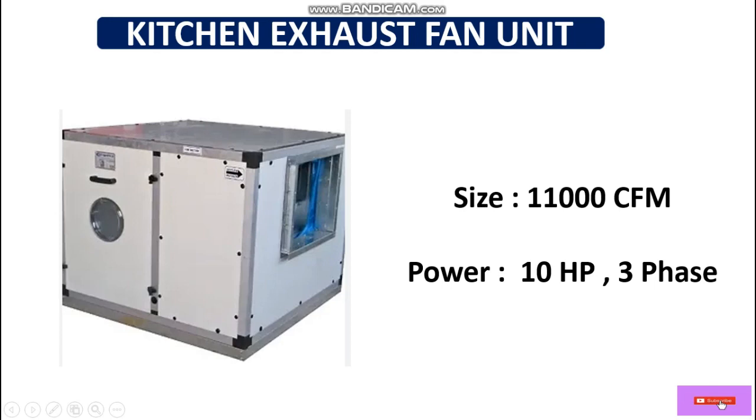So the capacity of the motor of this exhaust fan unit is 10 HP, which is more than 5 HP. That's why we have to use the star delta starter or VFD drive. So here we are going to calculate the size of the contactor for the star delta starter.